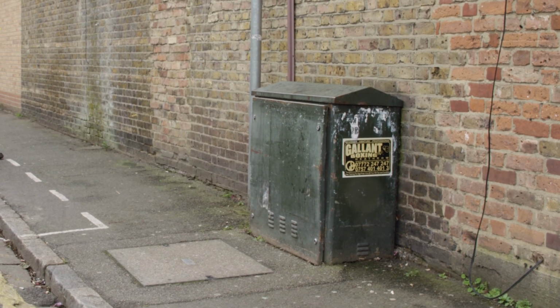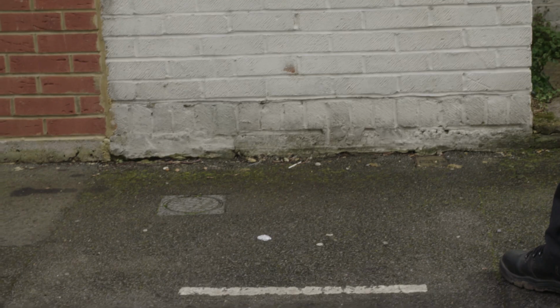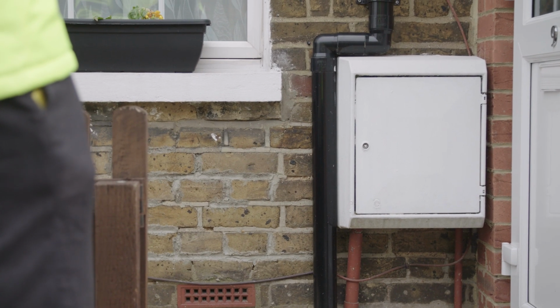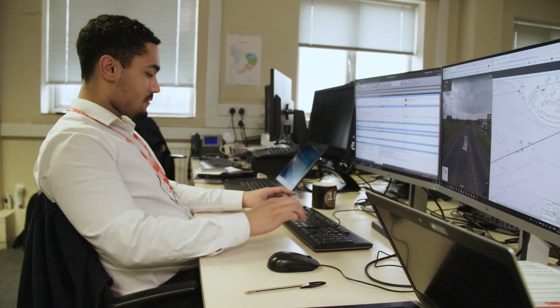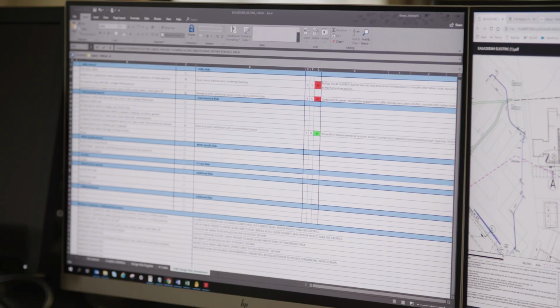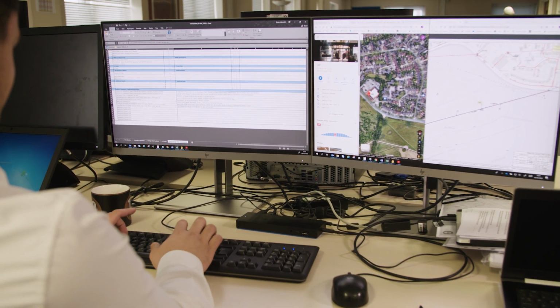Designers will visit the site, referencing the desktop surveys. They compile more on-site information for the plans, including proposed excavation locations and any visible obstacles, and optioneering around which methods of construction shall be employed. This will lead to the development of the designer's risk register and design risk assessment, which is a key component to removing any risks to the on-site teams.